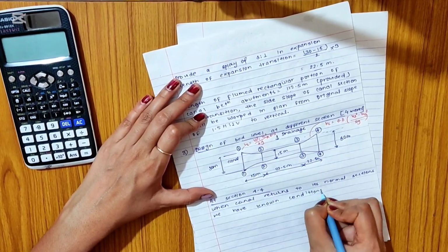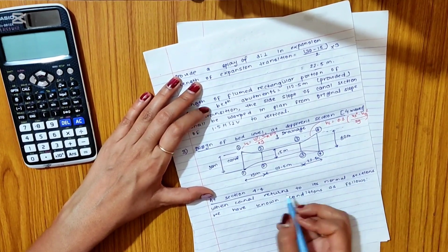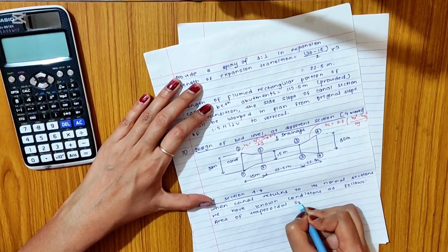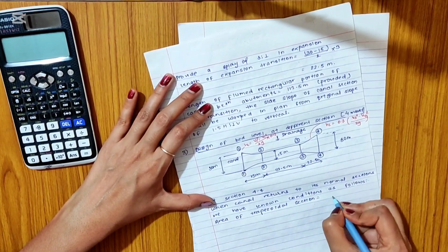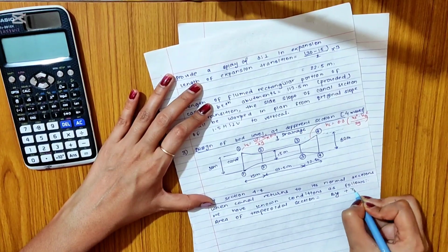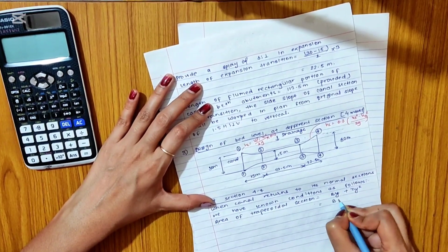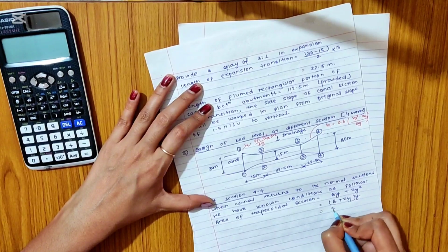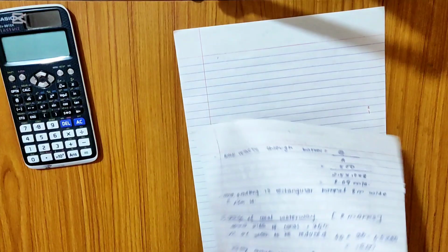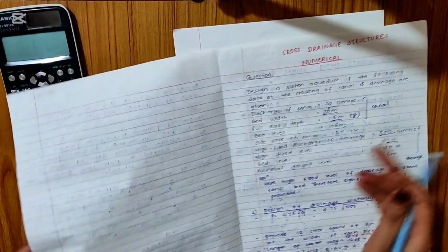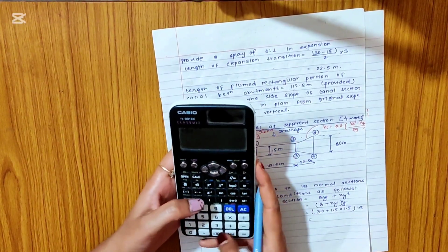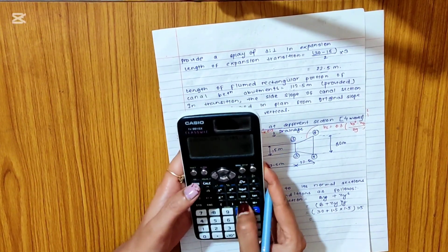The area of the trapezoidal section is (b plus zy) into y, which is equal to (30 plus, since z is 1.5, 1.5 into the full supply depth of 1.5 meter) into 1.5, which is equal to